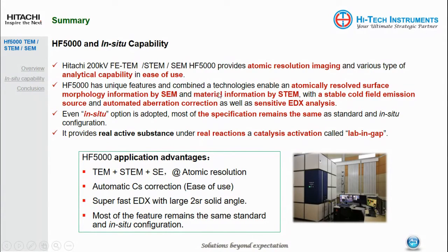It also combines technology that enables atomically resolved surface morphology information by SEM, which you observed in the video just now, and also material information, the Z contrast or the phase contrast by the bright field or dark field STEM detector, with a stable cold field emission source, and also automated aberration correction to observe atomic resolution as well as very highly sensitive EDX analysis. And with this in situ option adopted into the system, most of the specifications still remain the same. You can achieve the best quality even when you have the in situ experiment.